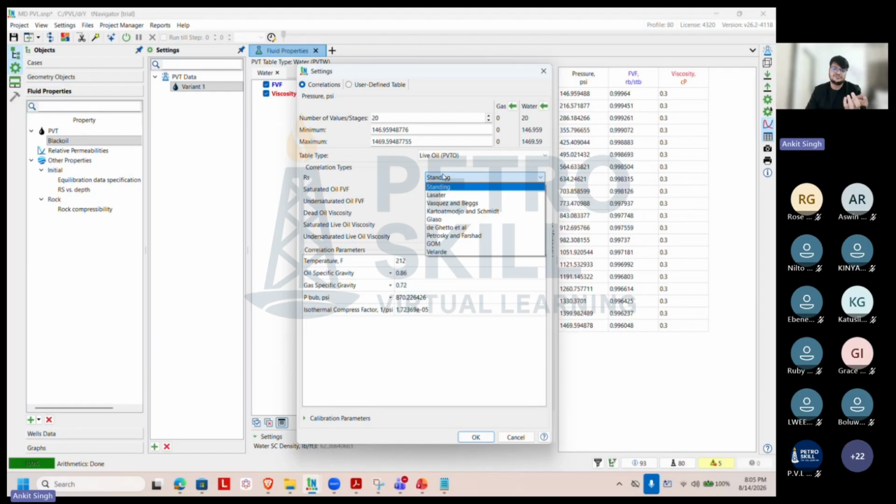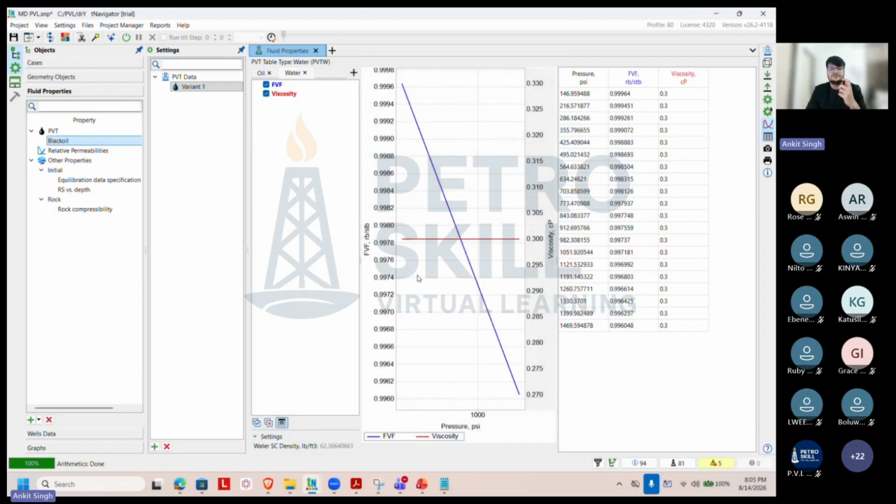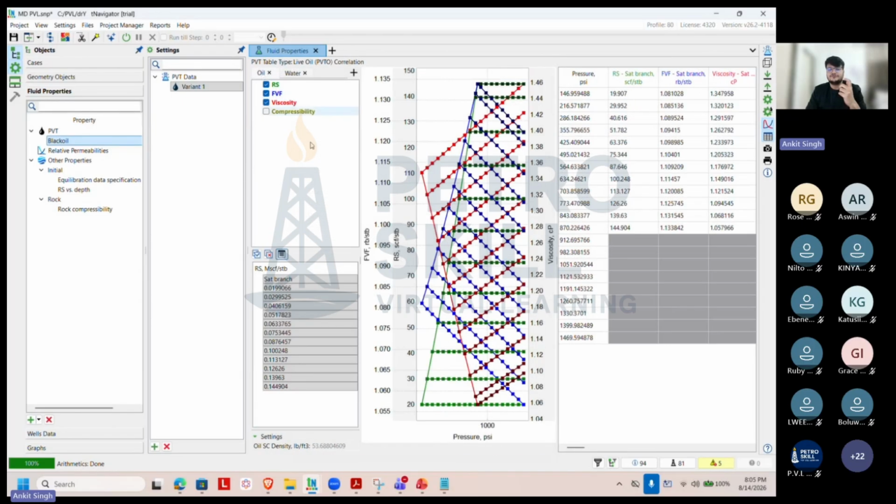What I'm going to do is replace some of the values here, bubble point pressure 1.733. Since this is dummy data, it will eventually match. Then we also have saturated oil volume factor, formation volume factors, as well as undersaturated, because we need to build that curve. Once I click OK, you will see that it has created a fluid model.